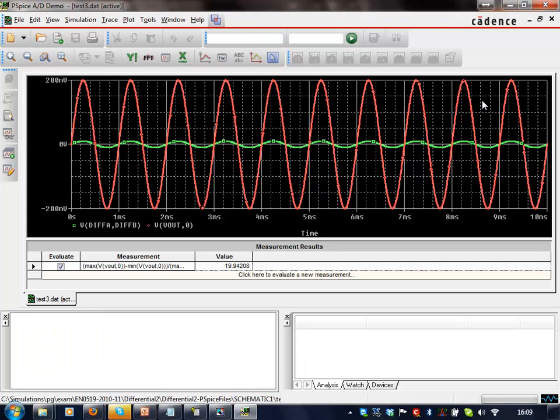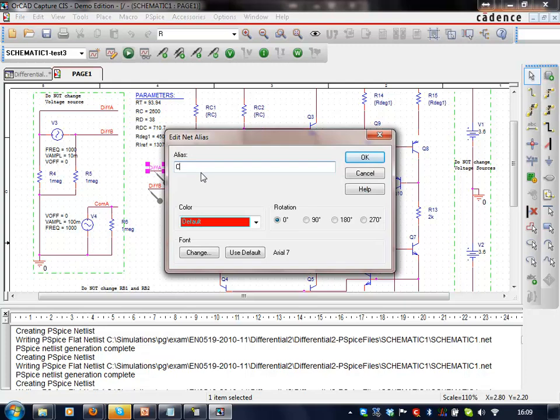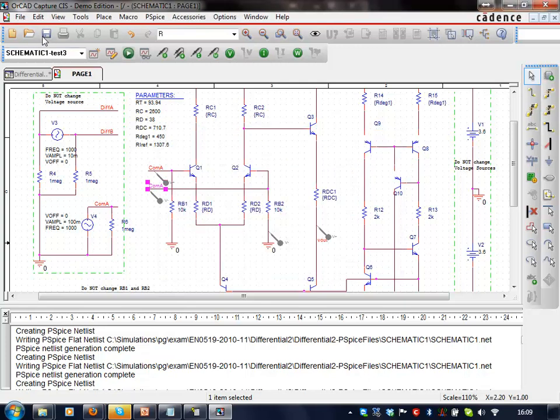Okay, so I'm going to close the simulator there, go back to here. And this is why I've got this circuit here. I can change this wire and change the label to COM A, and I can change this wire and change it to COM A. So now I'm putting the same signal in and I'm looking for any signal coming out, because there shouldn't be any signal coming out. So again, it's V out down to 0 and it's also common down to 0.